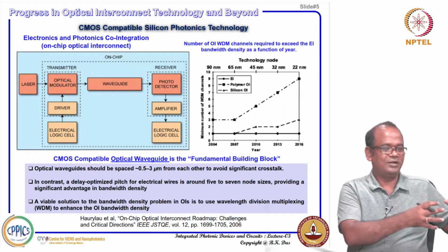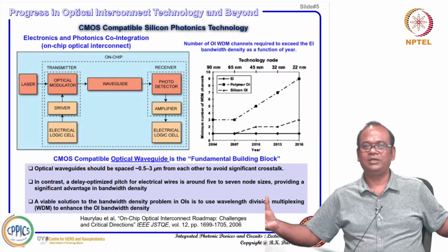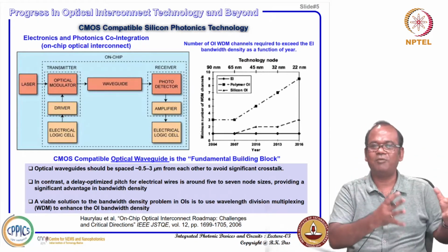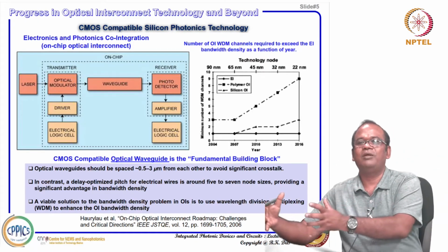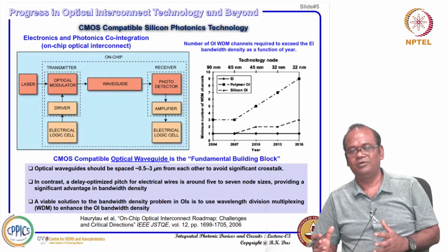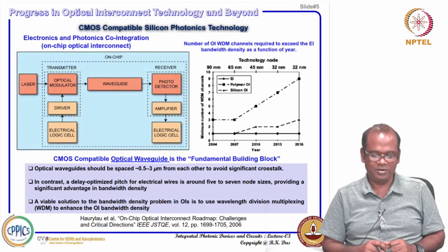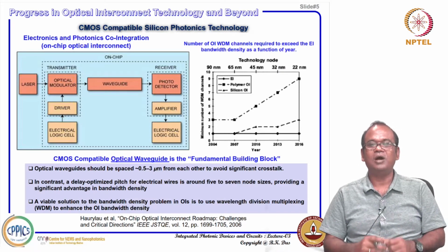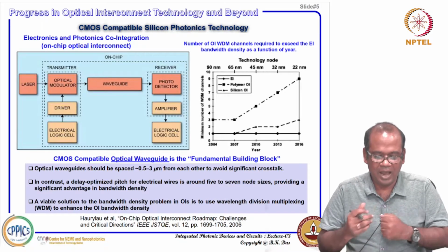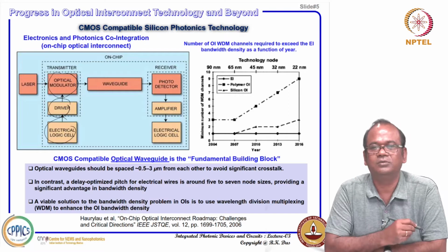Okay. So, you do not need a transceiver module, receiver module separately for that communication, right. You need to communicate from one particular block of electronics to another particular block of electronics within the chip, within the wafer. So, wafer scale engine can be demonstrated, that is what we have discussed earlier. Here one scheme is shown of how that can be possible. On chip, you have electrical logic cell and you can have driver electronics, and on chip you can have a modulator in silicon.